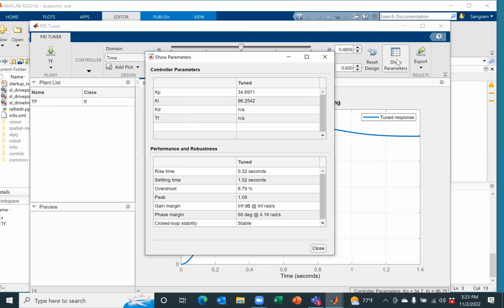And to be honest with you, that is not done by hand. There are MATLAB functions that will find the linear approximation, also called trimming. We do this all the time in aerial robotics. All aerial robots are nonlinear. So what we do is we trim or linearize the aerial robot about the operating point, and that linearized system is continuously controlled using the PIDs.